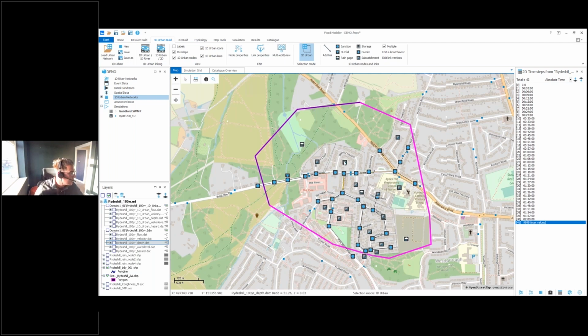We've got subcatchments. So if you're familiar with drainage network modeling, you'll be familiar with the subcatchment approach. Basically, each subcatchment defines the rainfall runoff assumptions associated with these discrete areas of the catchment. Those flows or the runoff from the subcatchment are then applied directly to corresponding manholes within the system. Then finally, this model has 3 rainfall hydrographs. Very similar to the way Kathy was applying before, we've got a rainfall time series, only this time they're being applied directly to the subcatchments so that the subcatchments can calculate those rainfall runoff losses.